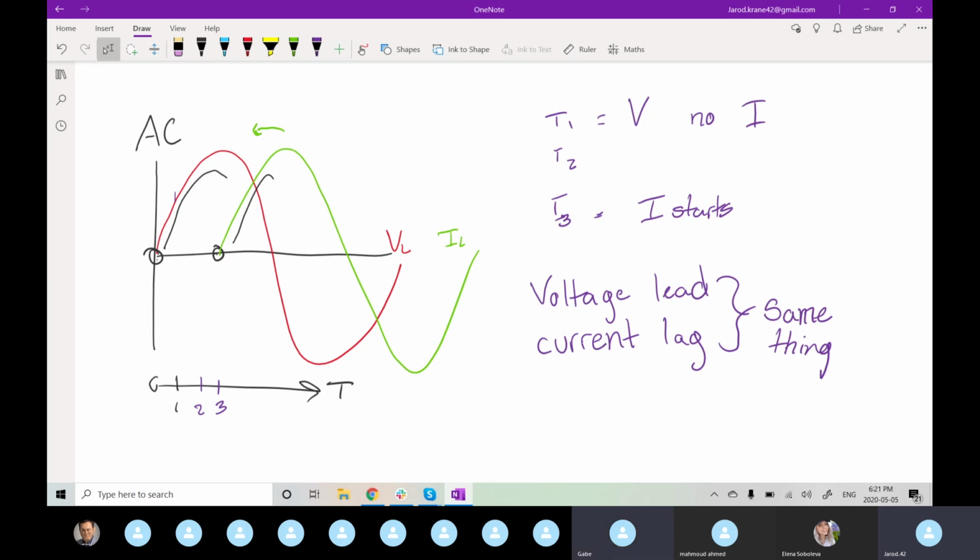There's a good application for this at the system level in the car, Mahmoud. Not really for the board, but for example, from the battery to the motor controller, you usually have some long wires, and those wires themselves add inductance to the system. And with too much inductance, when you're drawing current really fast from the battery, that current won't be just pure DC. It'll have a little bit of AC component, especially with a sharp rise. And so the inductance in those battery wires can add some unwanted voltage spikes to the motor controller.